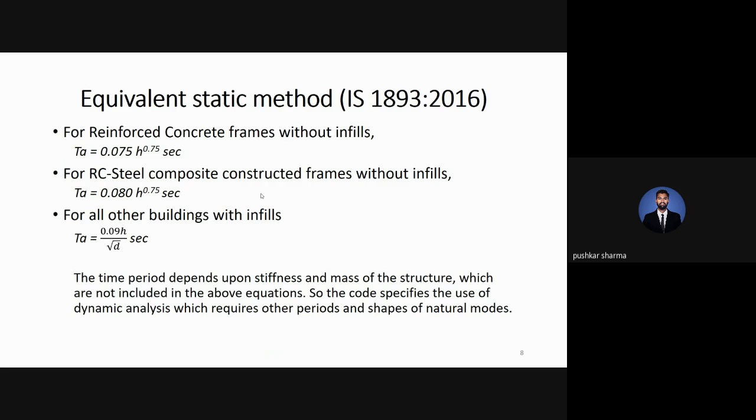As we all know, in the equivalent static method there are many empirical formulas to calculate the natural time period. Some of them are as follows, and the first formula is taken in this study because it is an RC frame building without any infill walls. The time period also depends on the stiffness and mass of the structure, which are not included in the above equations, so we move to dynamic analysis, which takes these parameters into account.